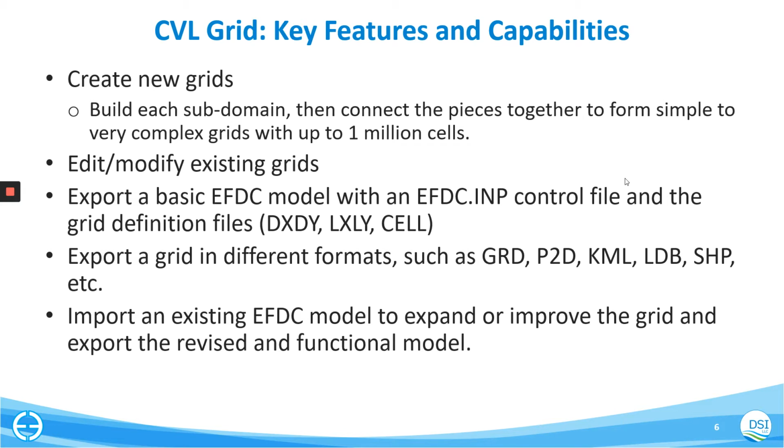We oftentimes export these grid and shape files or KML files to send to our client so that they can look at those grids and say, okay, if those areas are represented the way they wanted to see it. So KML grids help us. KML files can be opened easily in Google Earth. So any user who does not have access to EEMS or any other GIS software, Google Earth is free, so they can just open the KML file and look at the grid in detail.